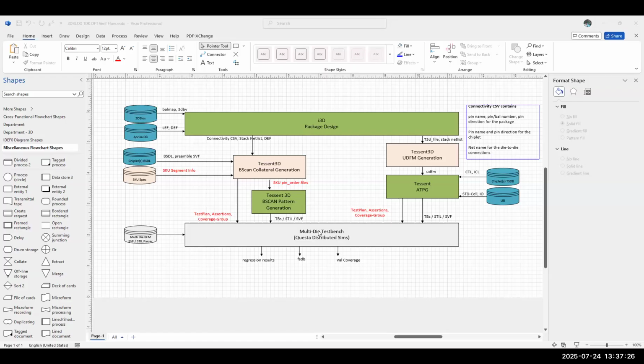Now you also have the ability to verify silicon interposers. If you have say two chips that are assembled on an interposer, you can test those chips through the interposer that's making those die-to-die connections. In fact, that's something that we supported when we were doing a chip with HBM memories, a very simple case where we had one big chip with 4 HBM memories. So what we would do is assemble the chip, mount the chip on that interposer, and then test to make sure that chip was assembled correctly before we would populate it with all the other HBM memories.